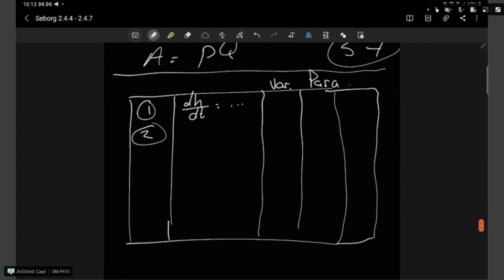So you can say, okay, well, here we have h, and this is my state variable, because it's the one that features in that term. And at a later stage, perhaps we have dT/dt. So we know, okay, so T is another state variable. And in here we have parameters a and u, etc. Perhaps that's As, and in this one we have another A. So rather do it like this, rather separate it completely after you've derived your entire thing, write it neatly in a table.